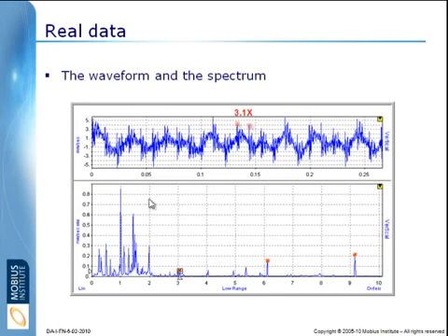Down in the spectrum, this peak coincides with the shaft rate, and this one marked in red coincides with this rate, or the frequency at which this is getting hit. And again, that is our outer race defect frequency in this case. These peaks over here are harmonics, or multiples of this one. They're also related to that rate at which that fault is getting hit by the balls.